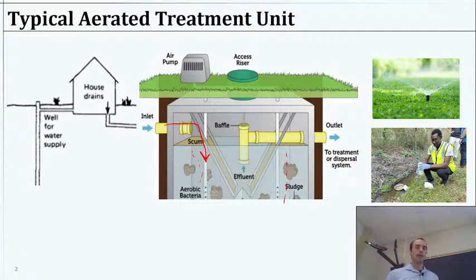In this case, it's a little bit like an upflow sedimentation chamber where water flows upwards. Some of it will make its way out, but in that process, there will be sedimentation along the way. So the water will slowly make its way and drain through here and be discharged from there. That's the scheme of it.